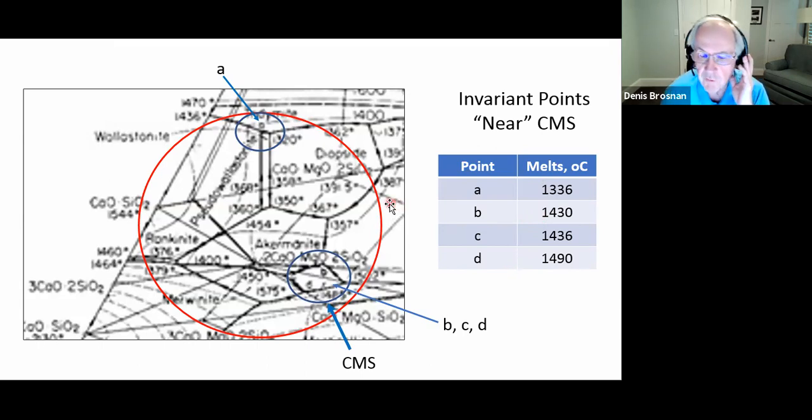So here's an important principle. On heating a ceramic composition, non-equilibrium liquids outside of the compatibility triangle can form and aid in the sintering process. Now, these in this circle are more likely because they're closer to the compatibility triangle, but we can't rule out liquid forming down at a composition represented by A up here.